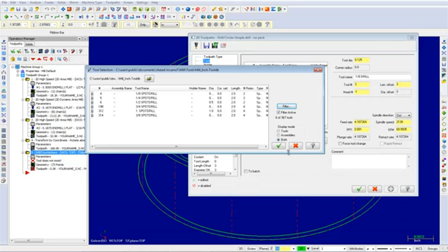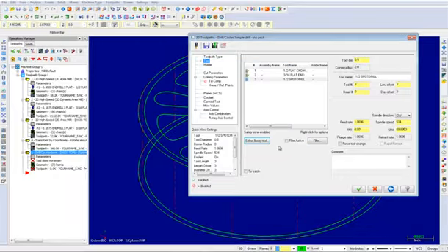At this point, you should only see spot drills. From that list, select the 1/2 inch spot drill as shown. You can now select the OK button. Your spot drill will appear as shown. Ensure that the spot drill is selected and then input the following comment.